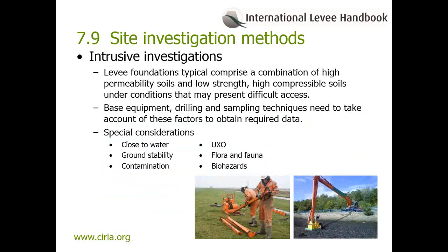When undertaking intrusive investigations, there is, as with all activities, a need to consider access and health and safety. As a levee is often located on soft soils, or on soils that have a high permeability or low strength, access can be difficult. Where such conditions are encountered, discussion should be held with the GI contractor to determine the best approach.